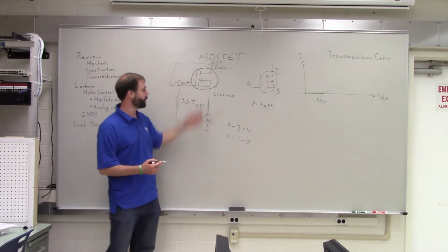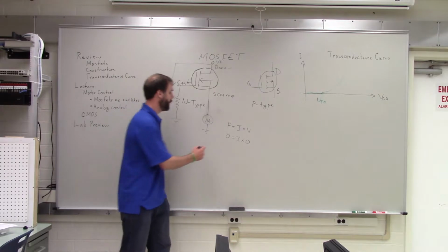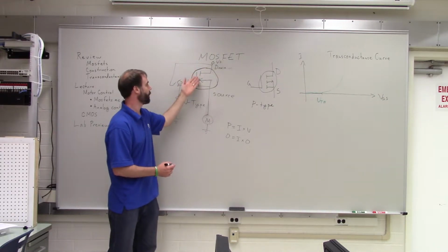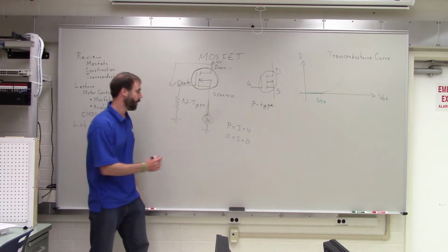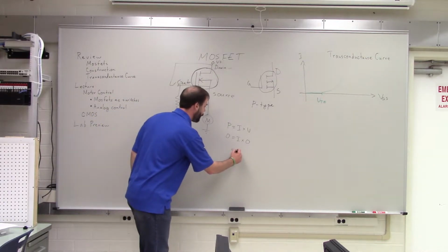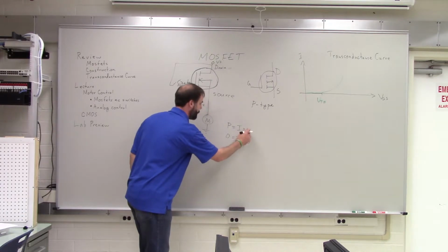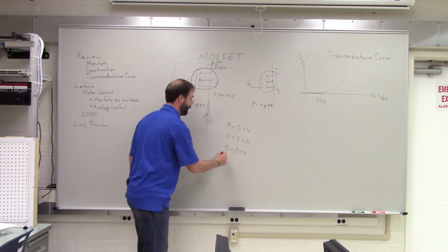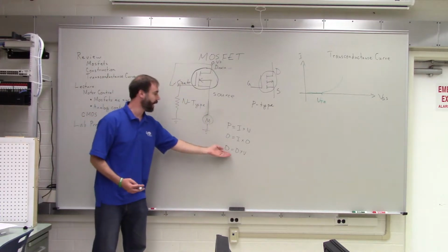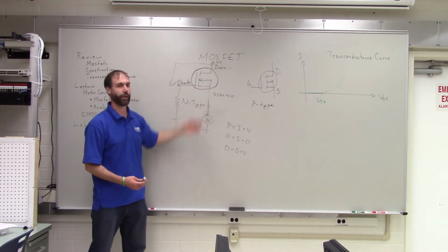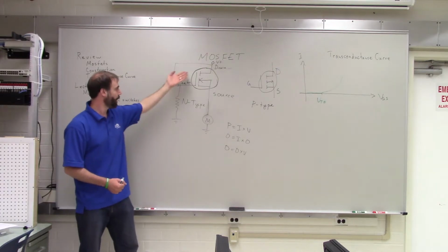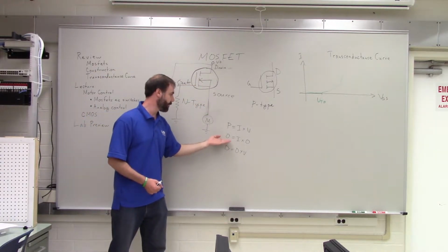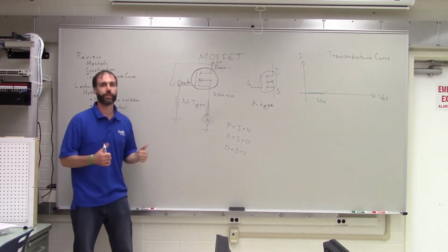Conversely, when the MOSFET is turned completely off, there is no current flowing through the MOSFET, right? So our power equation becomes current times voltage, and current is 0, so it's 0 times voltage. So again, we're using 0 power when the MOSFET is totally off. So when we use the MOSFET like a switch this way, it consumes very little power, right? So this is a good thing.